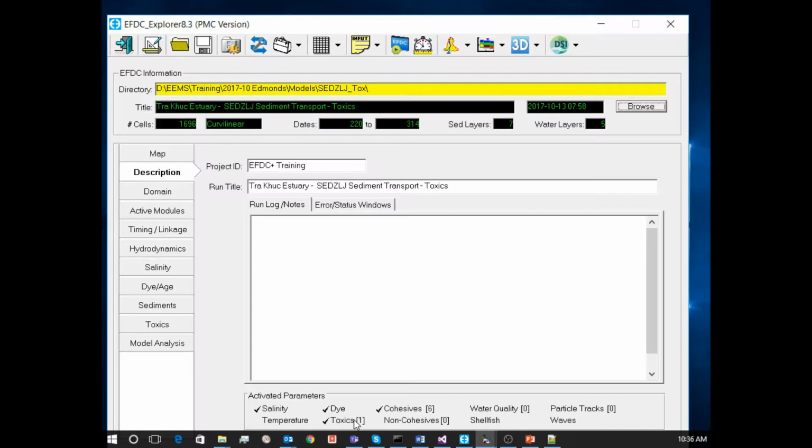But again, you still have limiting returns as you throw more and more threads at it, even with additional constituents. It does still help to pay attention to how many constituents you are actually simulating, and a little bit of matchup. If you had 13 constituents and a 4-core, no matter what you do, it's going to take 4 cycles to solve that solution.